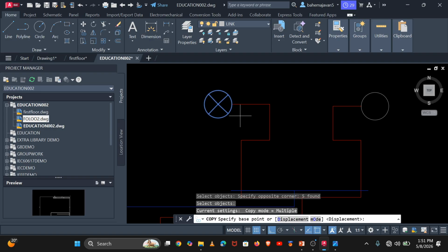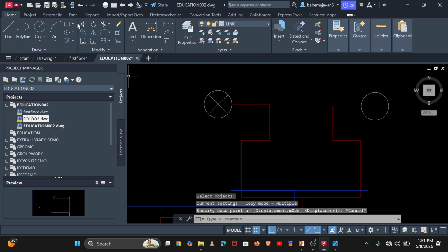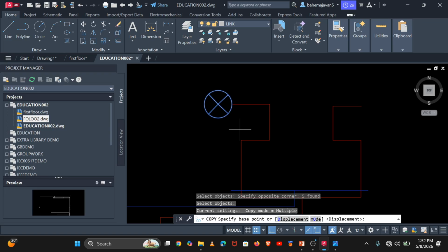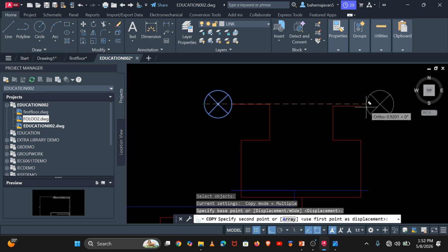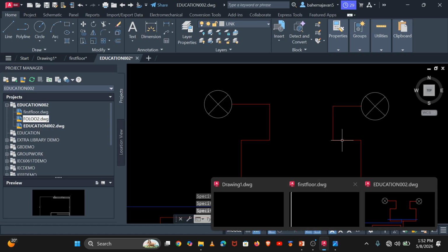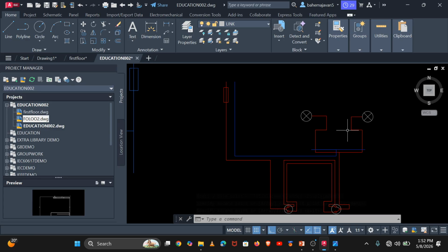So you can copy it like that, but the way I wanted to do it, let's first select this circle and delete it so that we grab the complete lamp. We just copy like this, and then click enter. When we click enter, then we choose the end point like this, then we grab and finish it here, finish by there, and then we hit enter. And you can see by this point that this is the first part of our electrical schematic.